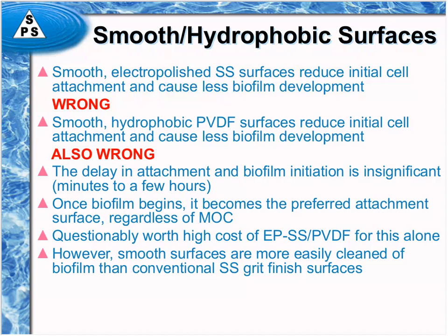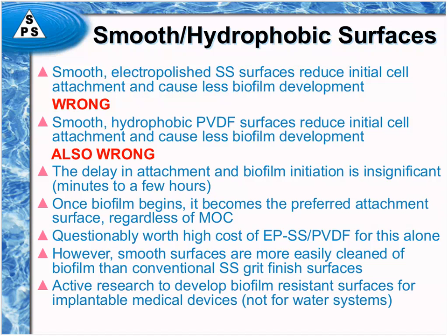With the absence of scratches and micro scratches in the surface, like you get with a stainless steel grit finish, you can have more cleanable surfaces, fewer hills and valleys to have to clean down into, fewer areas where organisms can hide away from the chemical sanitizers. And so there is a cleanability issue associated with smooth surfaces, but it is not related to the development of